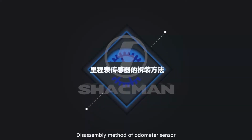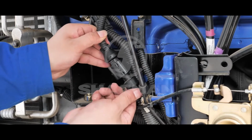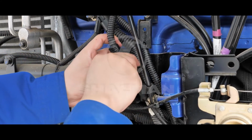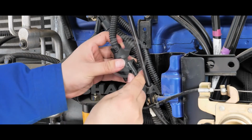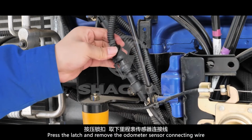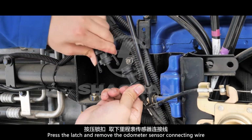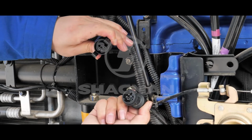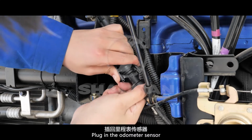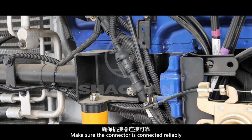Disassembly method of odometer sensor. Odometer sensor. Press the latch and remove the odometer sensor connecting wire. Plug in the odometer sensor. Make sure the connector is connected reliably.